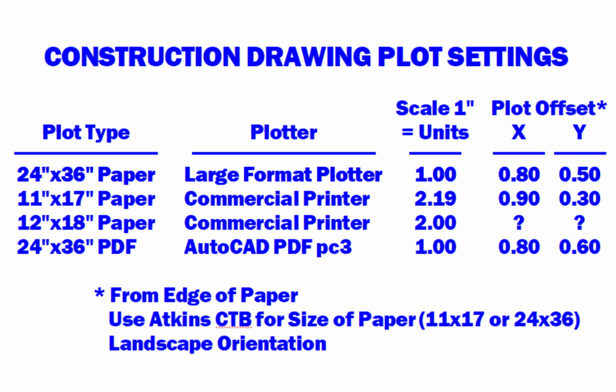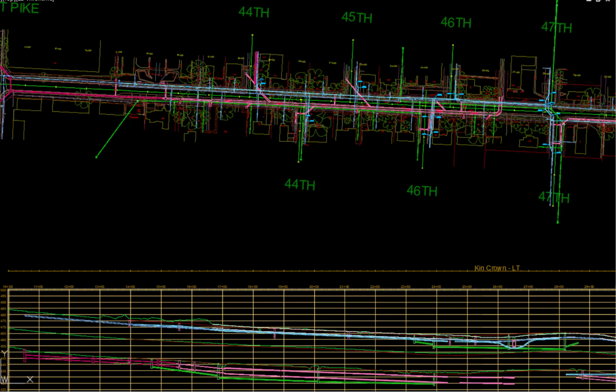A high-quality PDF file of the completed construction drawings is also created for submitting to contractors and construction advertisement companies. The PDF file is created with 24 by 36 inch drawings, which can be plotted on any size paper. Check plots are made at various stages during the preparation of drawings for review and editing purposes. A check plot is also made of the layout sheet to see how the various parts of the drawing will appear so that adjustments can be made to the settings prior to publishing the final set of construction drawings.